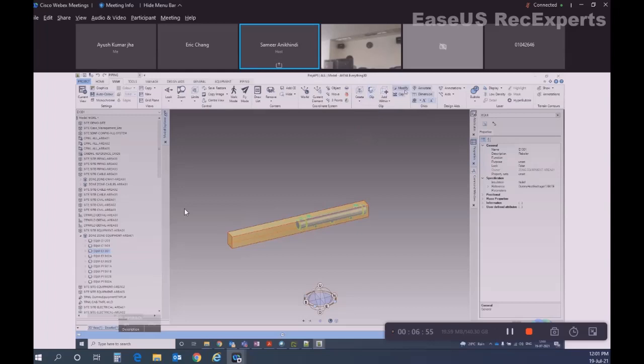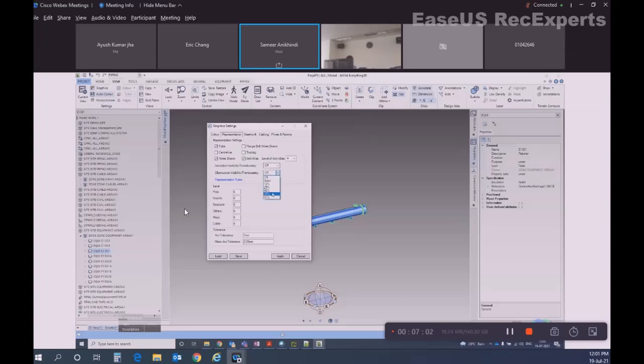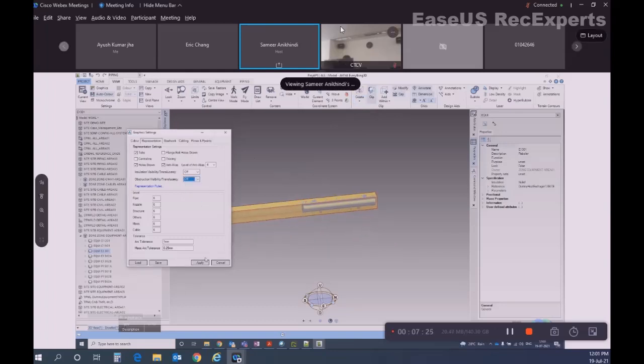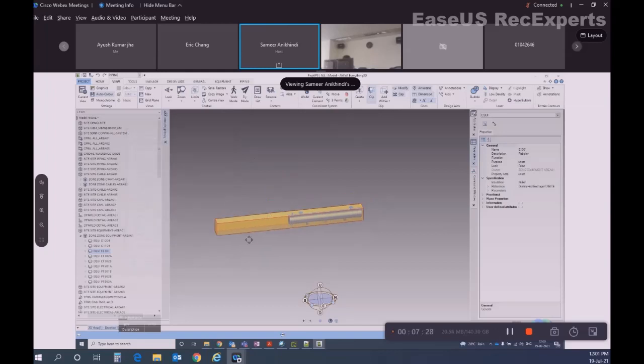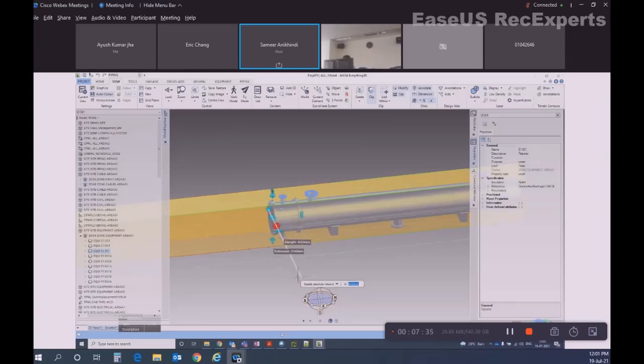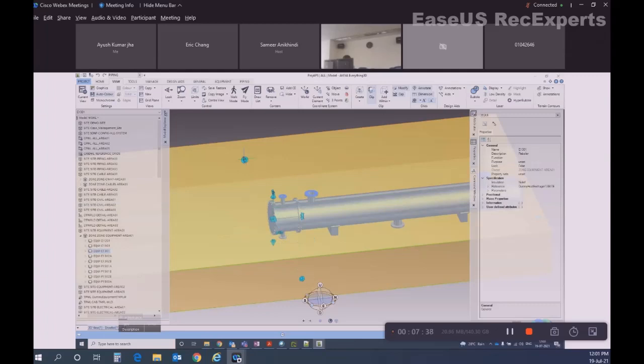So we'll go back, I'll make you understand. View graphics, turn on the obstruction. You see there's a tube bundle removal obstruction volume. That's why it is clipping completely. So if you clip current element of selection, it will consider this volume completely, which is not visible by default. Anyways, let me increase this volume in the height.